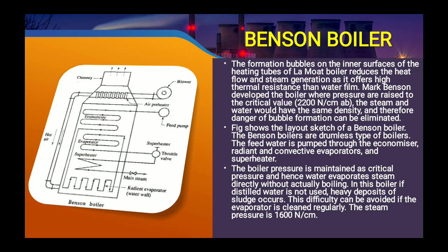In this boiler, if distilled water is not used, heavy deposits of sludge occur. So in the case of the Benson boiler, the water which is used to produce the steam must be distilled. This difficulty can be avoided if the evaporator is cleaned regularly. The steam pressure in the boiler is 1600 Newton per centimeter square. So this is the Benson boiler.